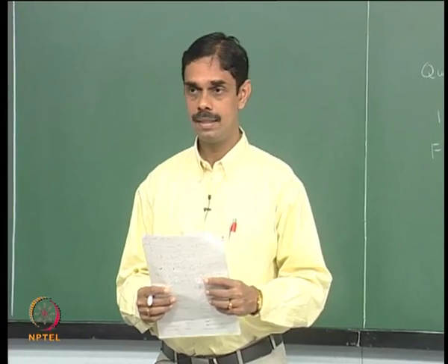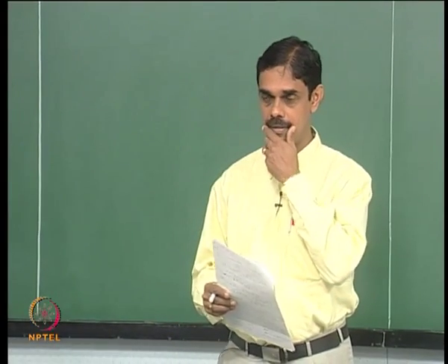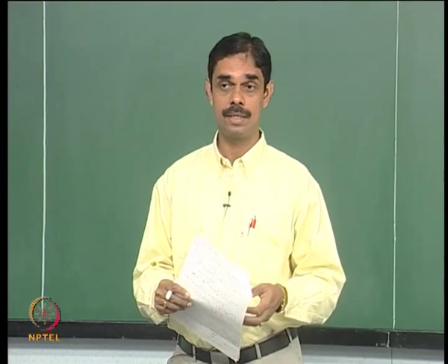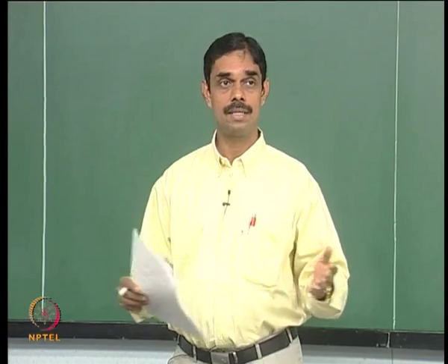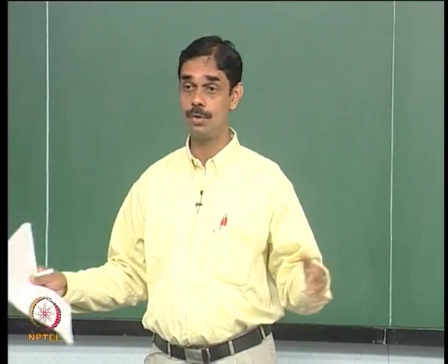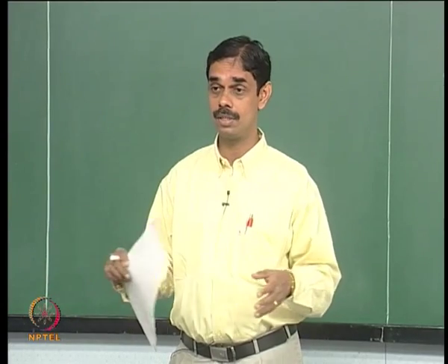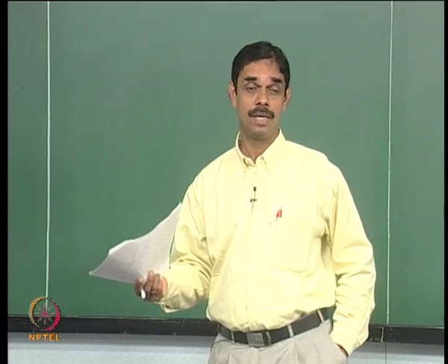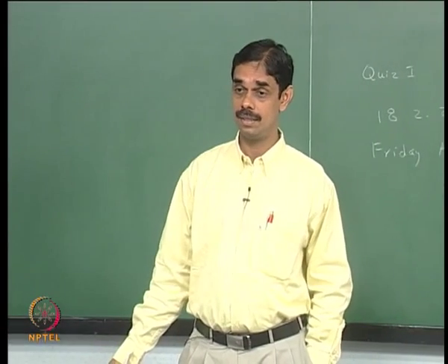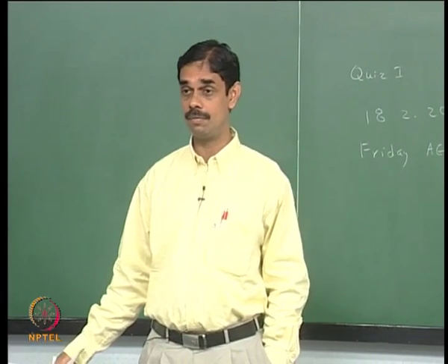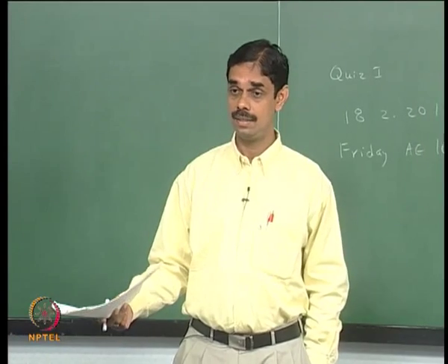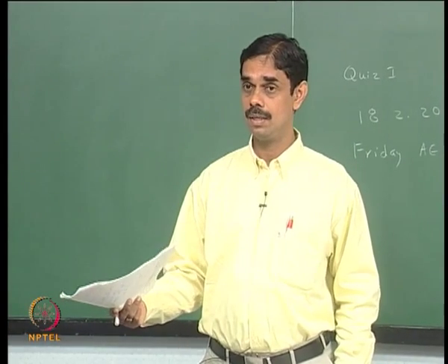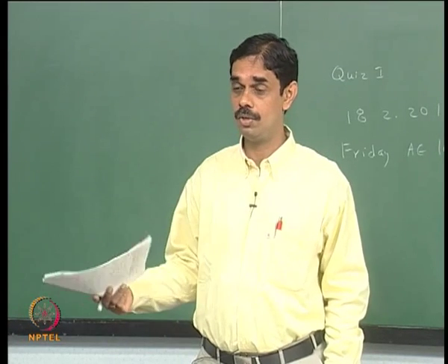So now I wanted to raise a question. We said that we have differential equations, and we can solve them as an eigenvalue problem depending on the boundary conditions. We need boundary conditions like open-open, closed-open, open-closed, and so on. But then the point was raised as to why a rocket nozzle would have exactly a closed condition and why it shouldn't be different, and I agreed that a nozzle will leak out some acoustic power, so you can have some non-zero value of admittance.